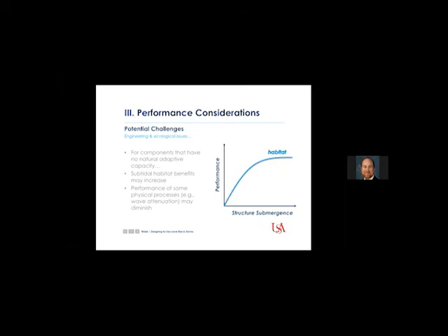So the habitat value really is going to increase over time. But your wave attenuating capabilities to stabilize the shoreline, or at least promote shoreline stabilization and reduce erosion, are going to decrease as that structure becomes submerged. And so you're going to have this trade-off, and it really becomes an optimization problem: where's the balance point, the sweet spot, where we can optimize this balance between providing good habitat in our structure, but also providing the wave attenuating capabilities that we need to address the forcings of interest.